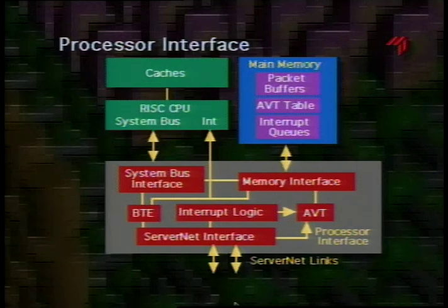This chip also includes interrupt logic to take interrupts, which are standard write packets in ServerNet, and queue them in main memory. The interrupt packets contain all the data needed for the processor to service the interrupt, and eliminate the need for extra transfers to read status registers on the I/O controller.